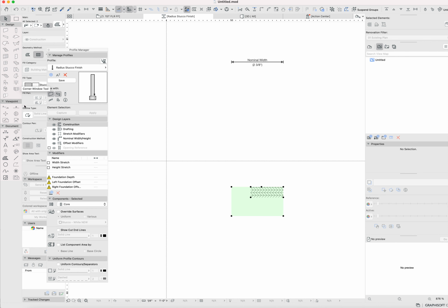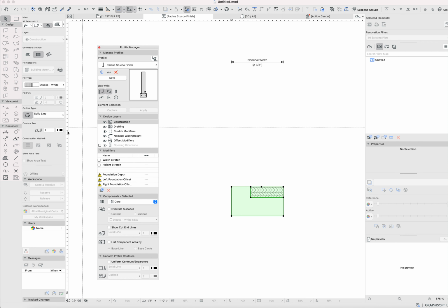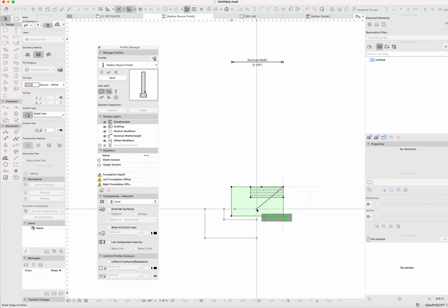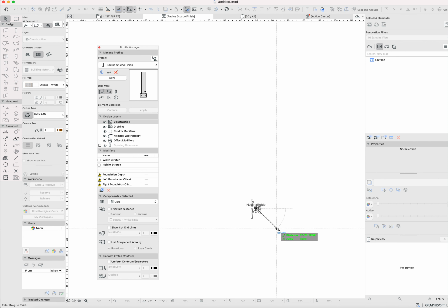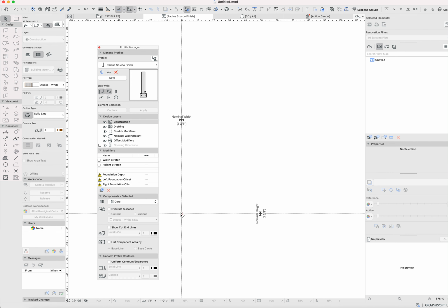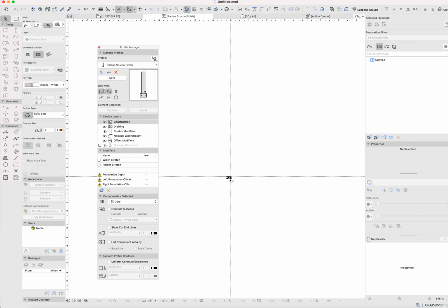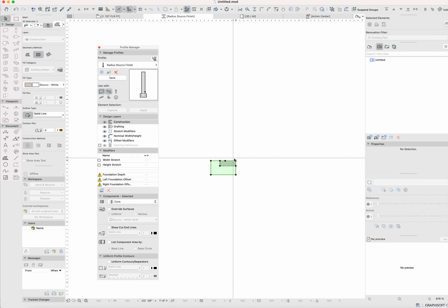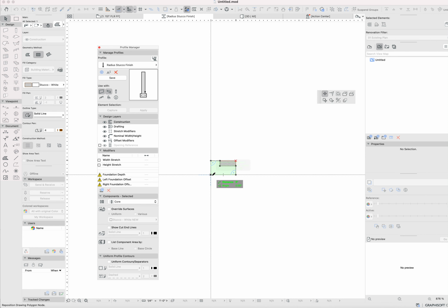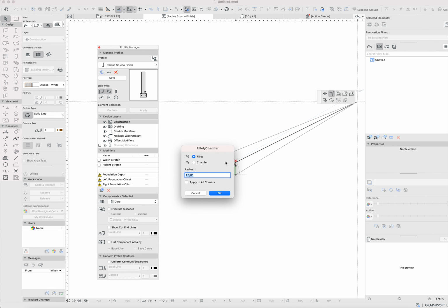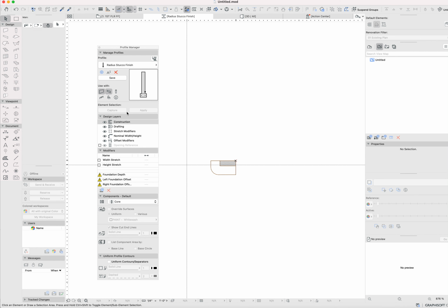And grab those fills. Let's go ahead and put a boundary pen on it. Ideally, I would match the pen that's being used at the wall settings. For now, we'll just leave it as is. And I'm going to put this on that corner right there for now. I can grab this corner using my pet palette, and we could say that this has a radius of, let's start at 3/4 inches. That seems to be good. We want this to be applied to beams and columns, and we'll say save.